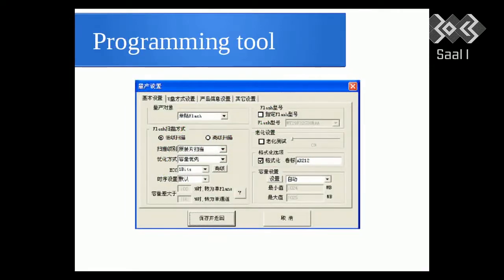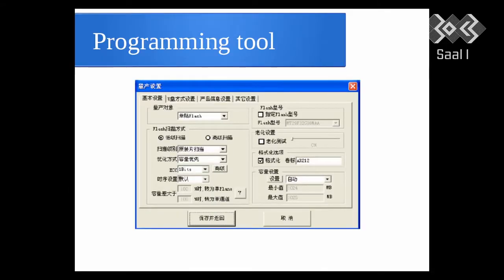So you open the programming tool, it runs on Windows, and you're greeted with this. If you actually translate this, there are some really interesting strings. You can figure out that this is setting every parameter for the SD card that you want to burn. You can set the manufacturer code, you can set the serial number. In the bottom right there, right now it's set for auto, but you can manually specify what it reports the card size to be. Which, if you're making counterfeit cards, that's a great box to have.